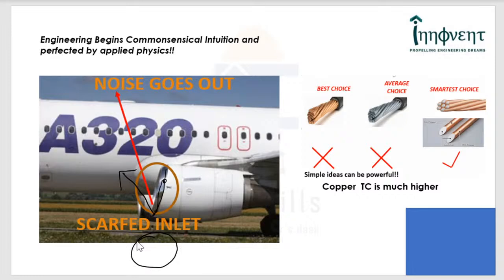Look at this simple example of copper and aluminum wires. Copper wires are far more effective in conducting heat, because their conductivity is almost twice that of the aluminum, and therefore they have a much better fatigue life. But aluminum is lighter and cheaper, copper is costlier.